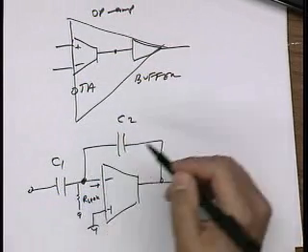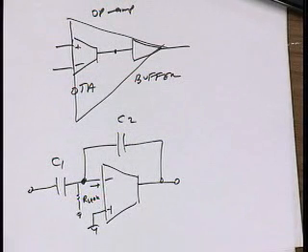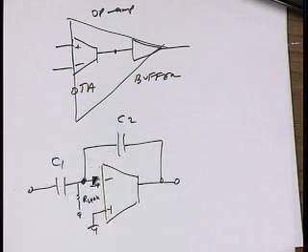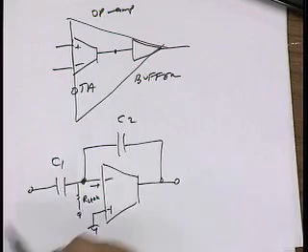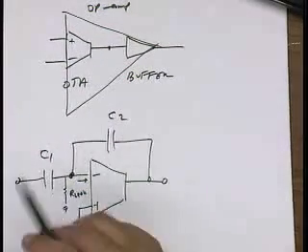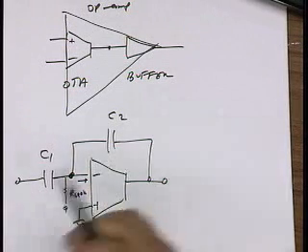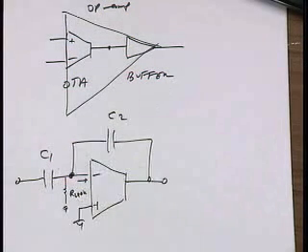I could discharge these capacitors right before I use the circuit, which means I need a clock. So really, this circuit, as I've shown it, unless I use resistors or unless I don't care about DC, will not work in a continuous fashion. I need to somehow stop the circuit, initialize the capacitors to a proper value, and then let the circuit run again.